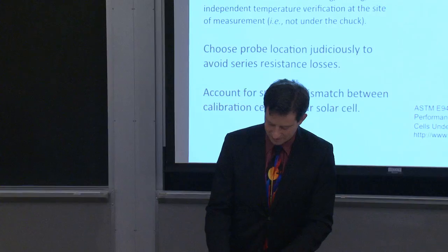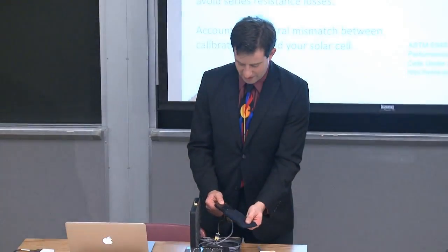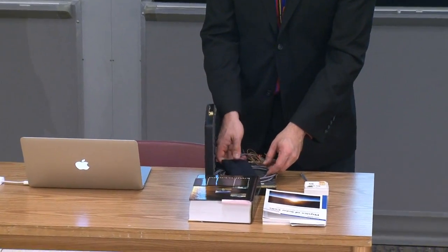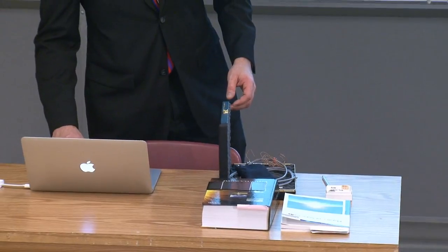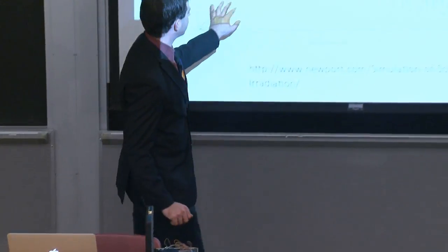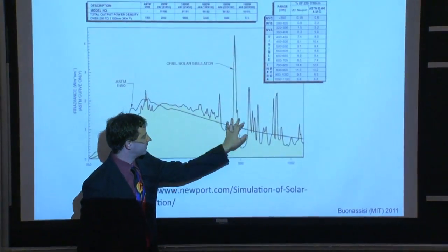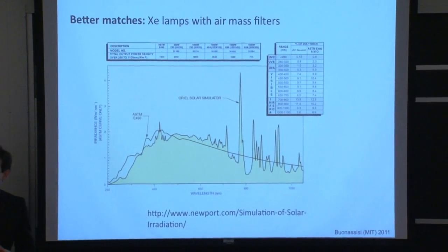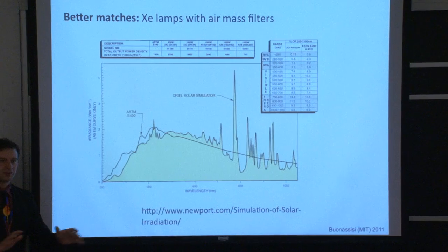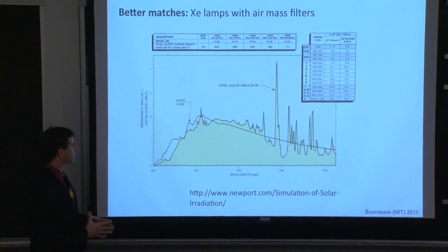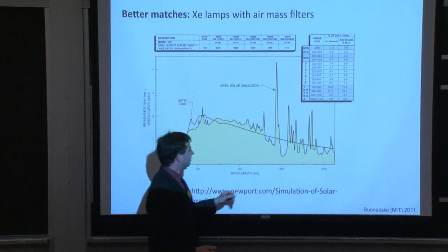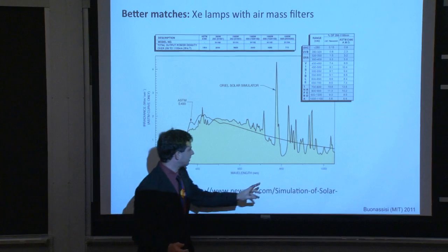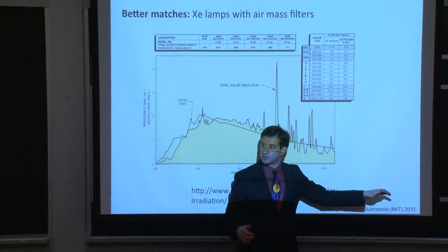So I have a crystalline silicon calibration cell right here. I know its spectral response. I know at what wavelengths it responds the strongest. And so it will detect any mismatch between the ASTM standard and the actual light source where it responds most strongly. Now let's imagine that I'm designing a new organic material that responds really well, pick something, in the infrared, right? And so now silicon will stop responding, let's say, at around 1100 nanometers. So anything beyond here, silicon won't be able to detect.